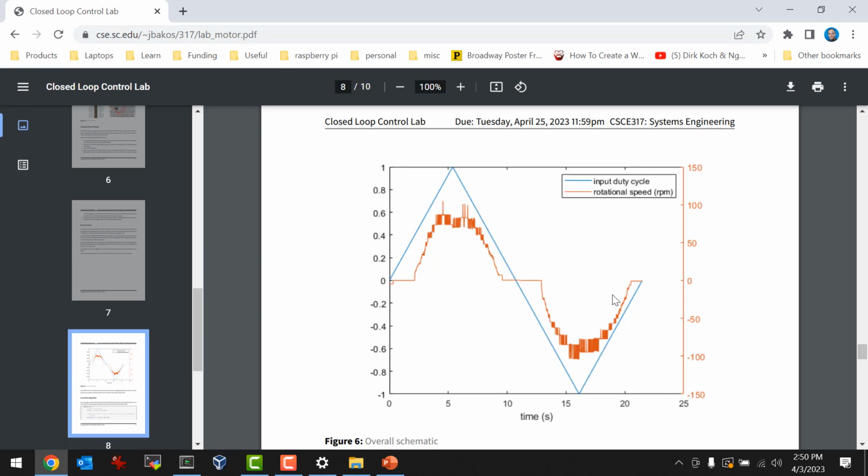So if the duty cycle is negative, the code just sends that duty cycle percentage out on one pin. And if it's positive, it sends it on the other. Does that make sense? So technically, my internal value of the power is between -1 and 1. You guys following that? Basically, it's just a duty cycle, the percentage that the PWM is on.